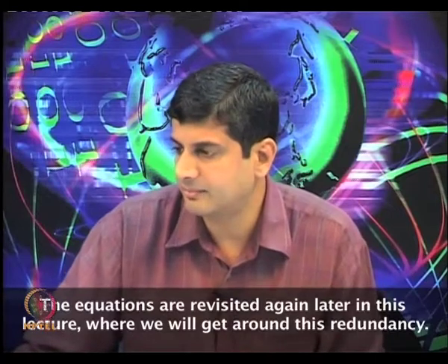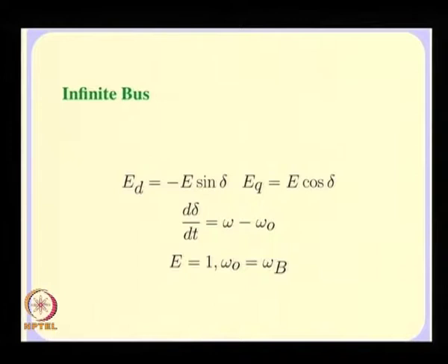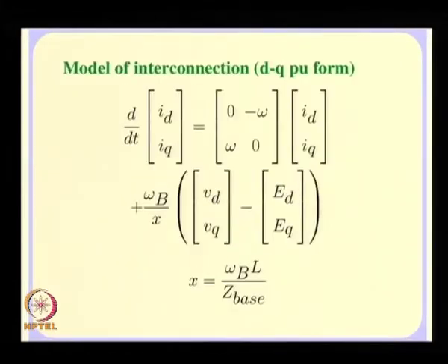If you look at something about the infinite bus itself, we are progressing towards finally getting our equations. We have not actually solved this earlier problem of redundant states. I have just told you that these states are redundant, because I_d and I_q are obtained by algebraic relationships with the states. So, how do you use this information usefully? That is something which you need to chew upon.